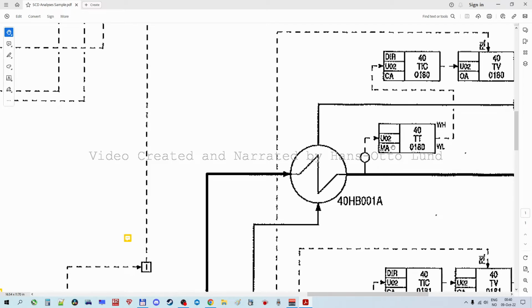And all those things here except that one, that is an ordinary tag, which is the name of that component. But there are many different types of codes here, function codes. And they describe how the block works, or different kind of properties it has. You need to use that NORSOK I-005,